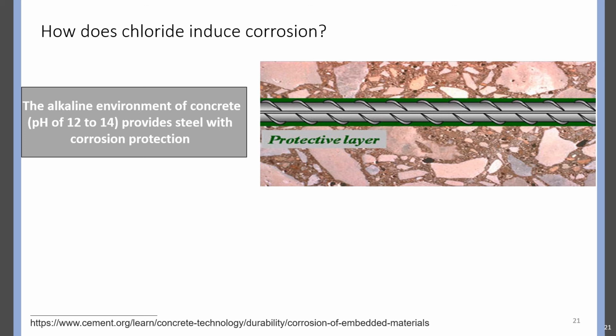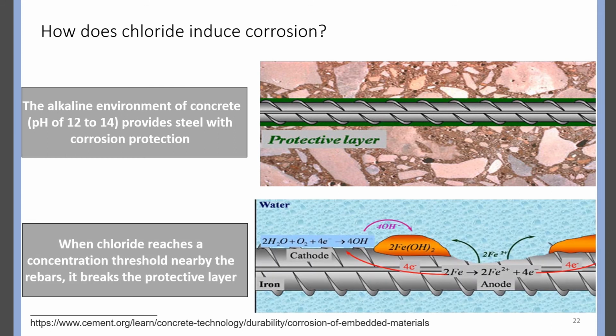In the specific case of chloride ingress, the protective oxide film integrity of the reinforcements is controlled by two processes in competition: the repair or stabilization of the film by hydroxide ions, and the film destruction by chloride ions, which is also called depassivation. Depassivation of the reinforcing steel occurs when a sufficiently high chloride ion concentration is present on the steel surface.